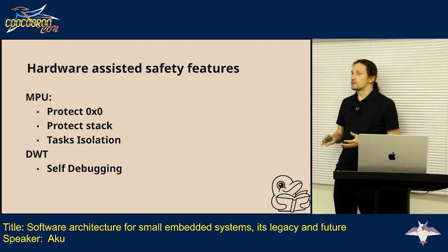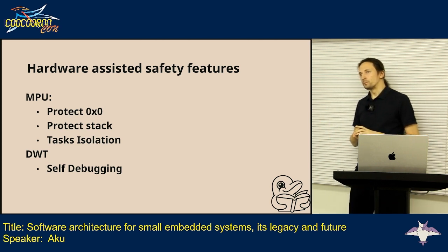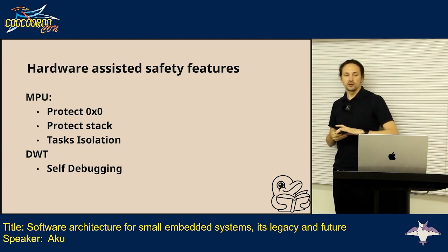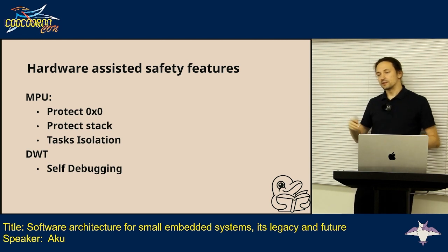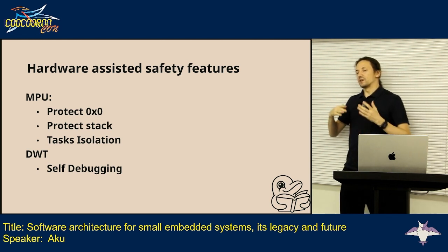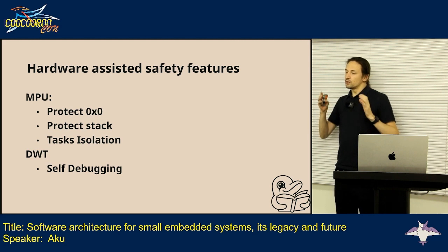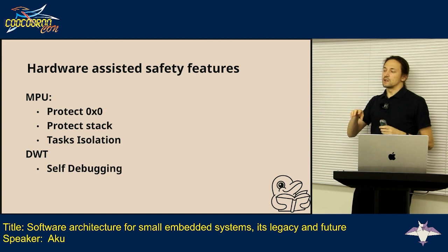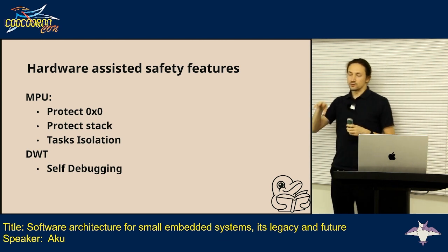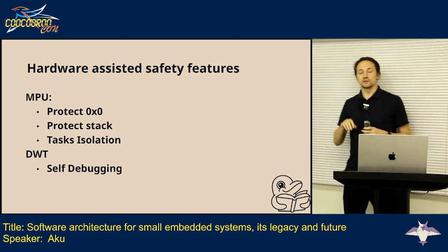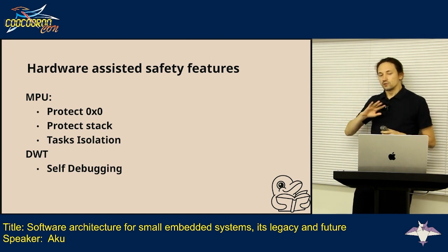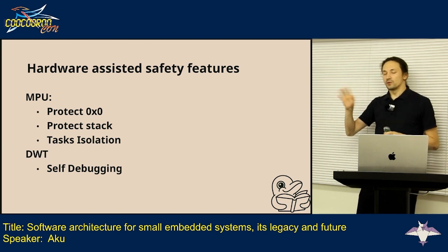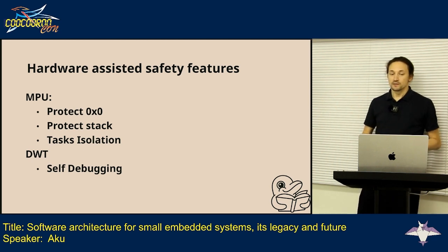Also, that's probably the most simple MPU usage. For those operating systems and software specifically designed to work with MPU, you can extend MPU support in your operating system to the point where, for example, your task will be fully isolated and it can only access memory allocated to this task, including the stack allocated to this task, and forbid this task to corrupt memory or do something with memory outside of this sandbox.